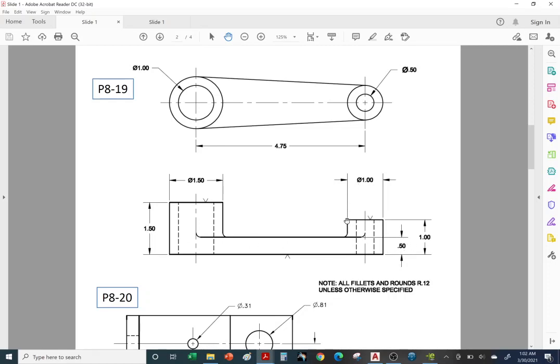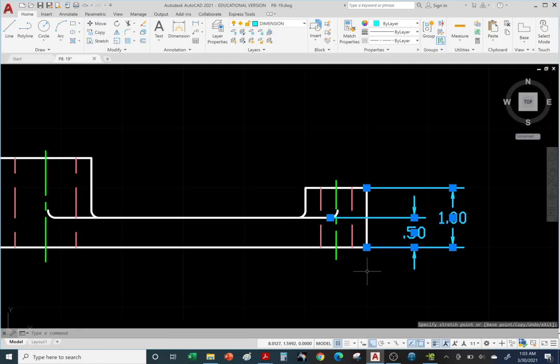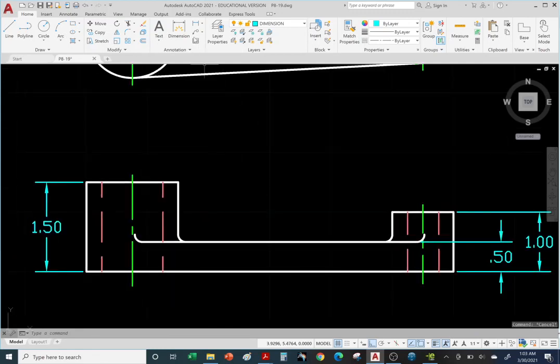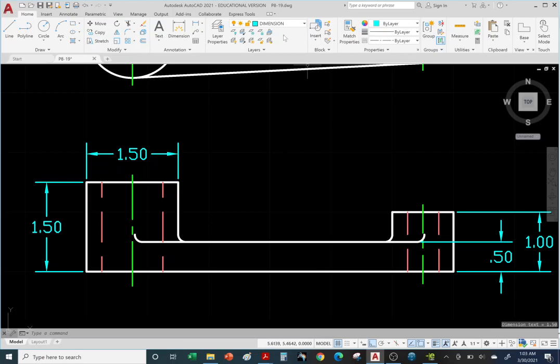Okay, let's throw in the diameters for the shafts. If it's a solid circle, you don't dimension the circle, you dimension the rectangular views. Let's go ahead and throw in these two dimensions. Before I do, let me space these out a little bit further. They're just a little too crowded. All right, there it is. Hit escape on the keyboard. Okay, so let's throw in linear dimensions. Linear. From this point to this one. Same thing on the other side. Linear dimension again.